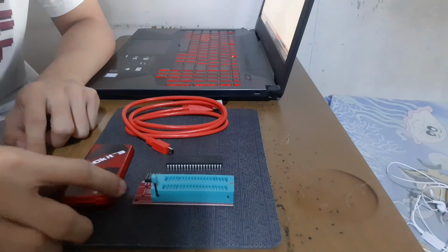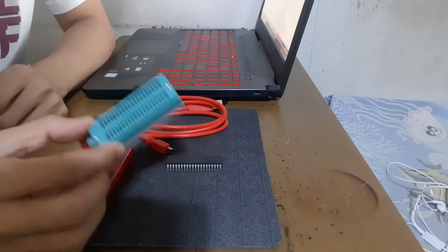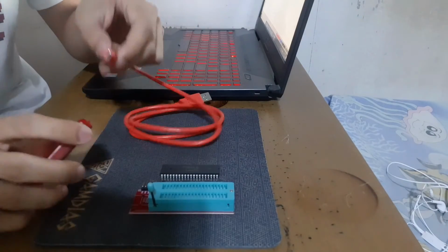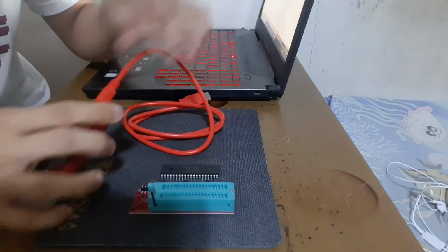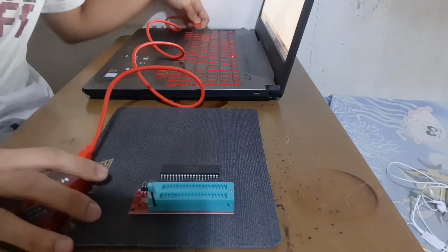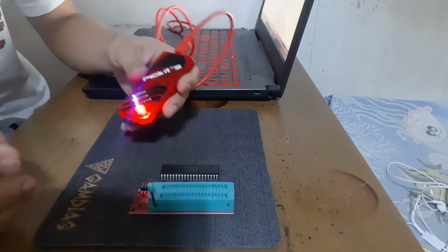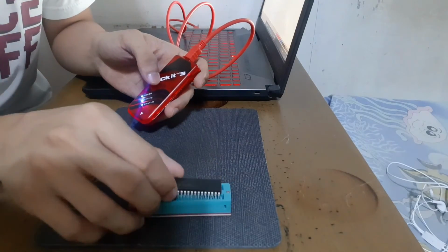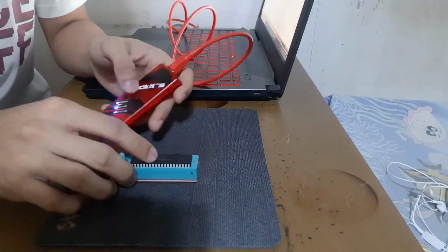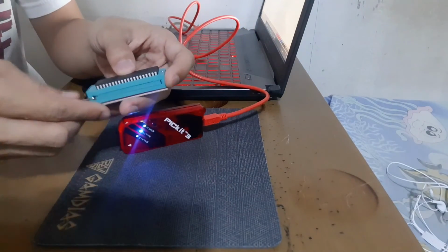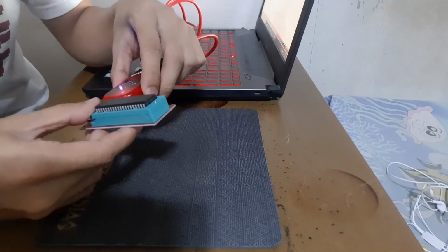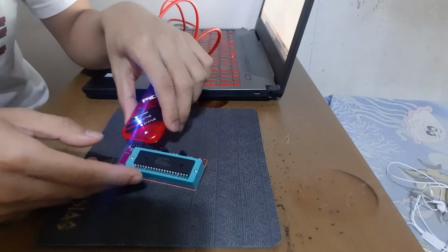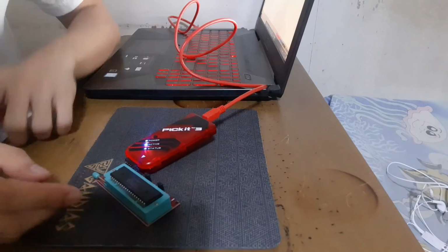To install the program we created, we will use our PICkit 3, ICD2, IC, and USB cable. First, connect the PICkit 3 to the personal computer. Next, place the IC to the ICD2, then pull the lever down to lock the IC. Last is to connect the ICD2 to the PICkit 3. And now, we're all set.